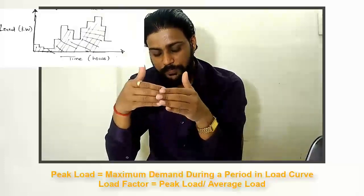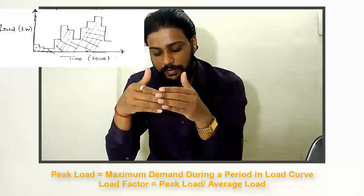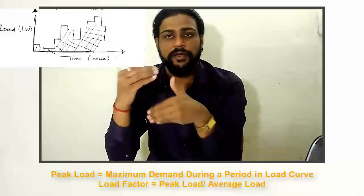If you are considering a simple house, the same scenario will be there if you add up everything for a full city, and also if you add up different factories and so on. So the load will be varying. The graph of the load with time is known as the load curve. Before you study power plant engineering, you will need to know what the load curve is. Again, there would be something like the peak load, and that is the maximum demand which I said.